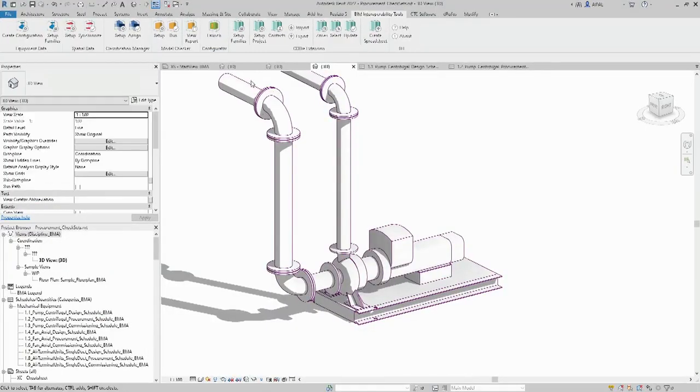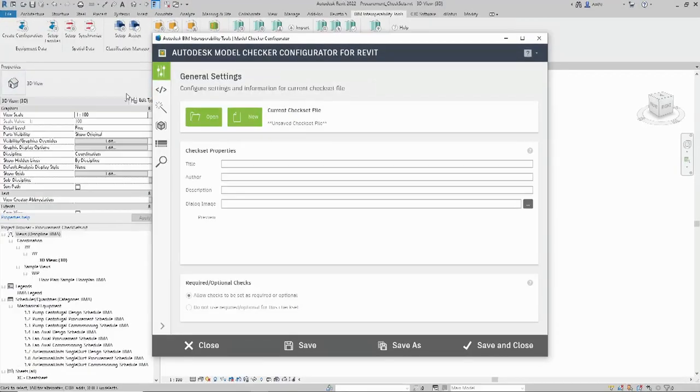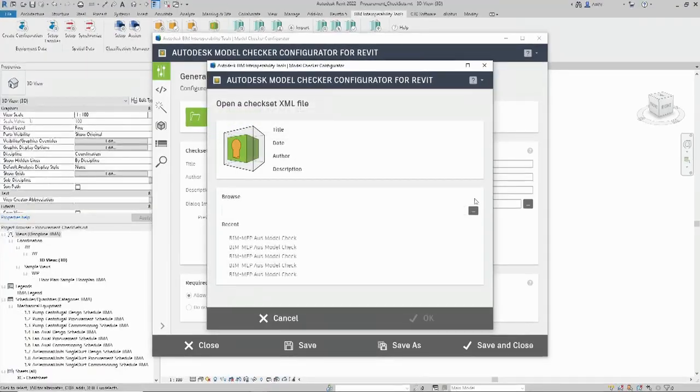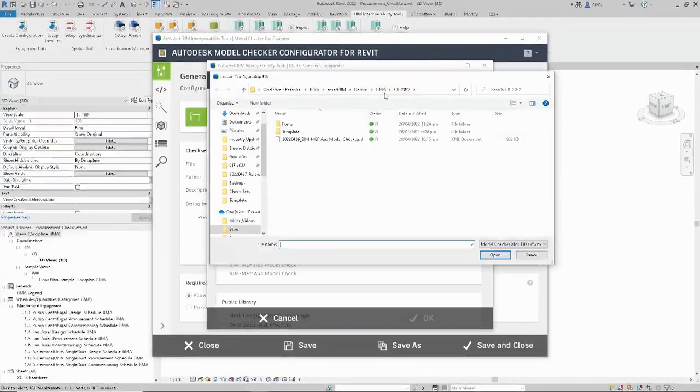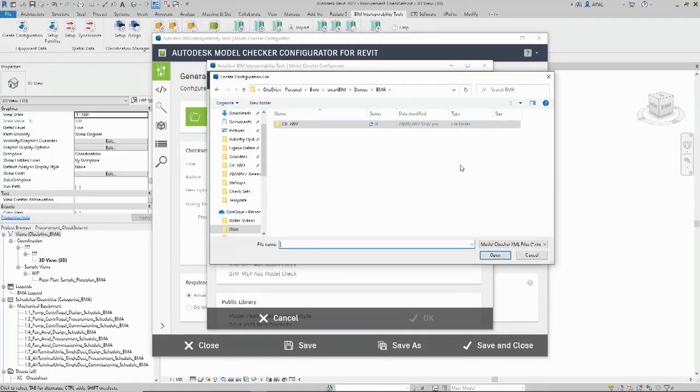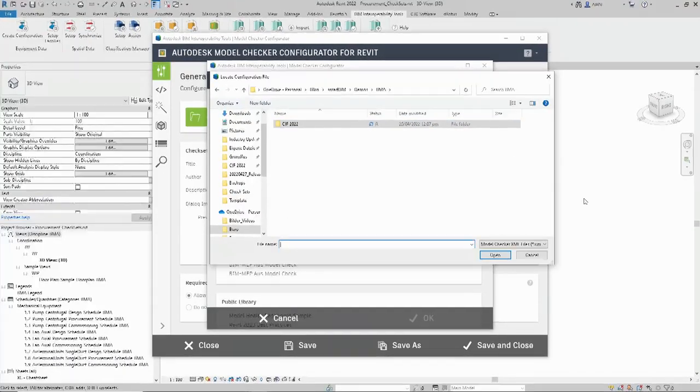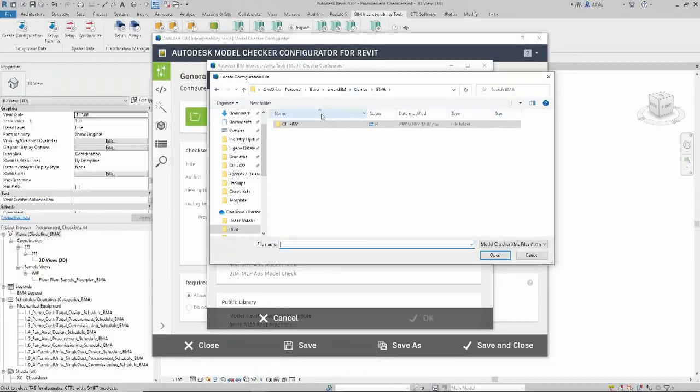just go into that configurator again, just to give you a bit more background. We also have defined GUID check sets based on GUID. What I've shown you so far is just looking for the parameter name. But I already mentioned before when we spoke about the schedules, that of course in the background that GUID needs to be right.